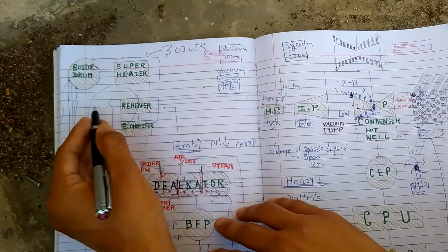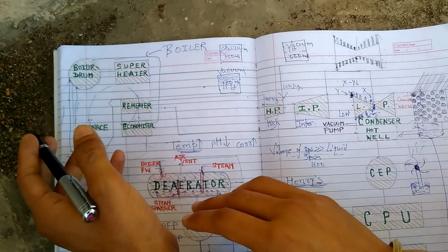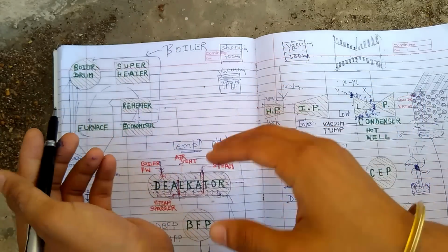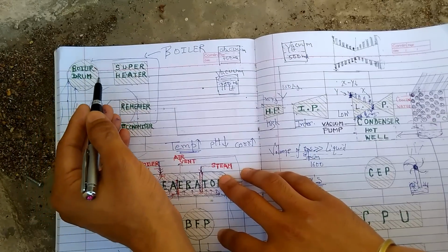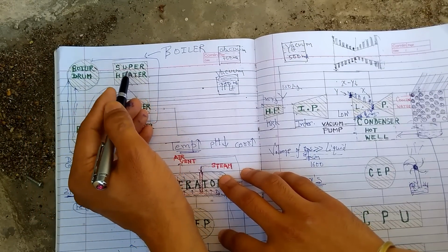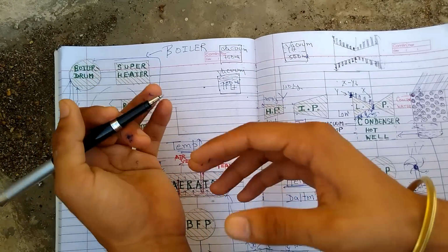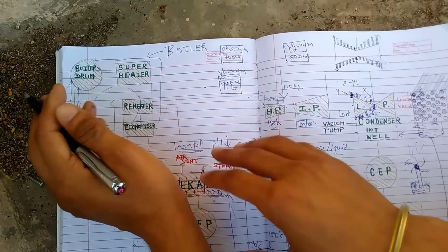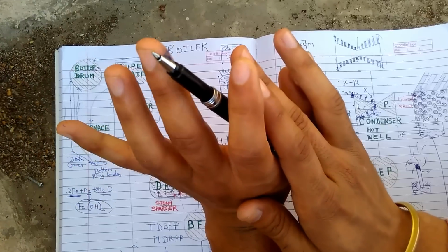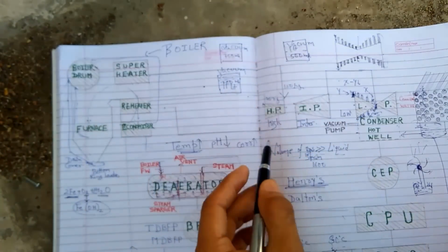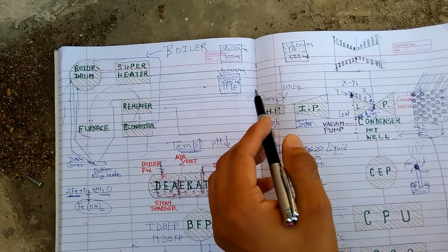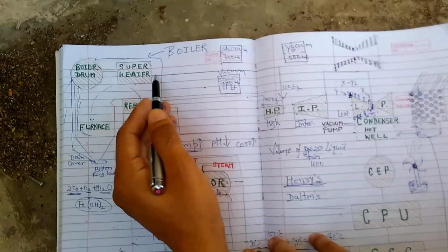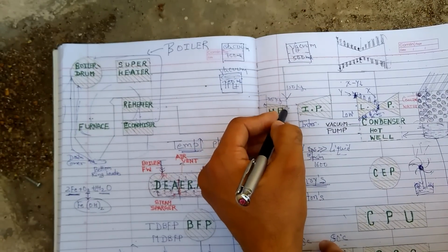Even after getting a higher temperature in the furnace, my water contains some particles of moisture. To remove those moisture particles, I have to superheat it, so I send it to the superheaters. They may be in multiple stages: low temperature superheater, platen superheater, final superheater. After superheating, my steam is totally moisture free, because I do not want moisture to be injected onto the turbines, as that may corrode the turbine metal. So after that, superheated steam is sent to the turbines.